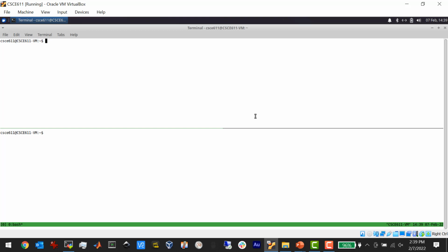Yes? But it is still possible to do your own exception handling, right? Sure, yeah. Yes, you can. The problem with the memory part that I was referring to is that you need a memory management unit to do that kind of memory checking, and the Nios processor actually does have that as an option. We don't usually use it. We just use a physical memory space.